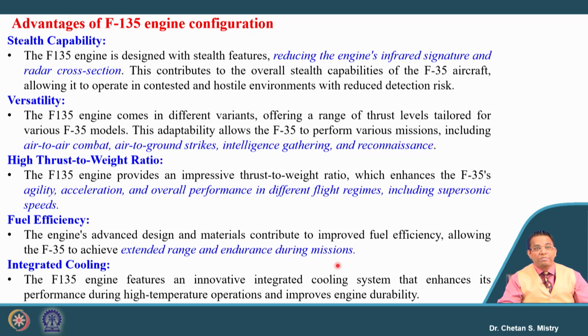engine. At the same time, it is having a high thrust to weight ratio as we have discussed, and that is giving the agility, acceleration, and overall performance under different flight regimes, including supersonic speed also. And fuel efficiency is one of the major attractions. That's the reason why the range and the endurance limit for the mission are extended. Here, since it is working under a very high temperature configuration, a special kind of attention is required in terms of cooling. That has been taken care of in the F135 engine.